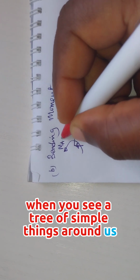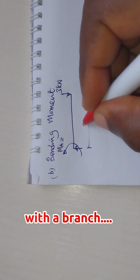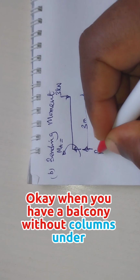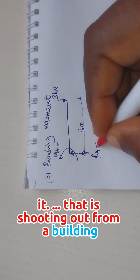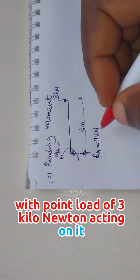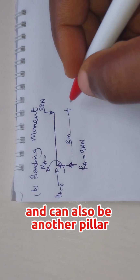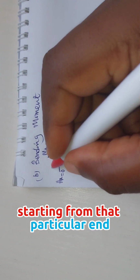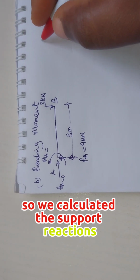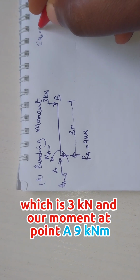When you see a tree, simple things around us, that's a cantilever, with a branch. When you have a balcony without columns under it that is shooting out from a building, that is a cantilever. So we have this cantilever with a point load of 3 kilonewton acting on it. This point load can be a block wall and can also be another pillar starting from that particular end. So we calculated the support reactions, which is 3 kilonewton, and our moment at point A, 9 kilonewton meter.